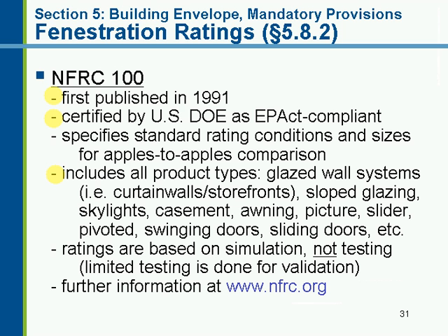The ratings that you get out of the system are based on simulation, not on testing. So if you're used to doing testing or thinking about testing for structural or for air leakage and water leakage, for U-factor and SHGC, it's based on simulations, though there is some limited testing that's done for validation. For further information here, you can refer to the NFRC website at nfrc.org.